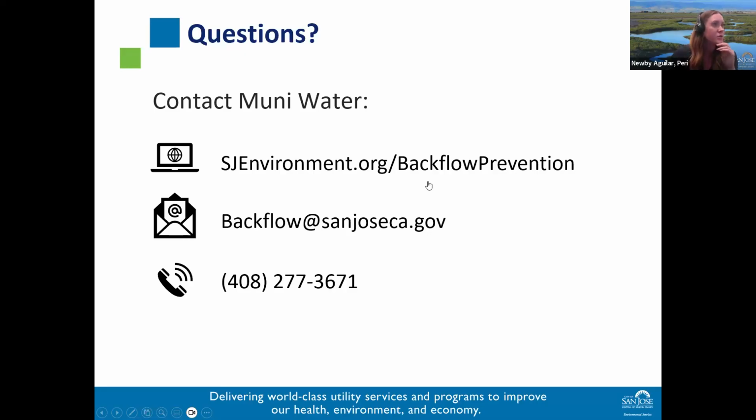Does every meter to the house have a backflow prevention device? If not, why not? For single-family residential homes, we do not require what we would call a containment backflow prevention assembly. Those are much larger devices. Single-family residential homes have not historically created high hazards to the extent that we need to require a backflow prevention assembly.